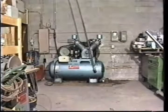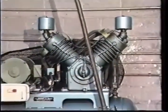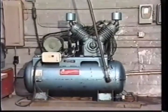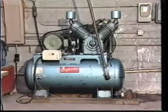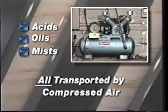Drying and cleaning compressed air for use in manufacturing, fabrication, and research applications is critical to the success of the operation. Let's briefly examine the problems that can be caused by compressed air. The air discharged from a compressor is usually hot. Cooling it causes condensate, which can contain particulate material, oil, and other contaminants. Corrosion in pipelines can add to the particulates. Additionally, acids, oils, and mists are all transported by compressed air.